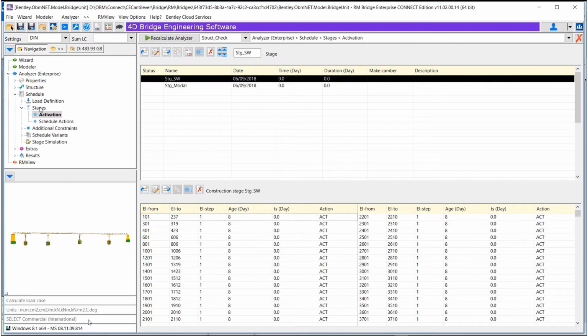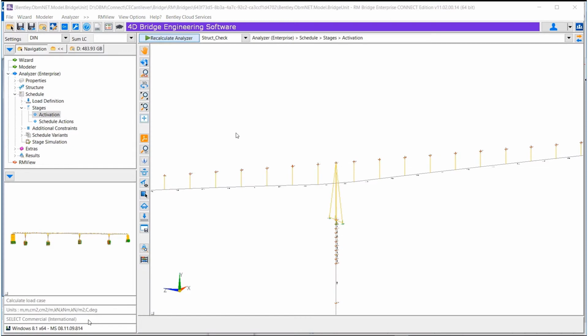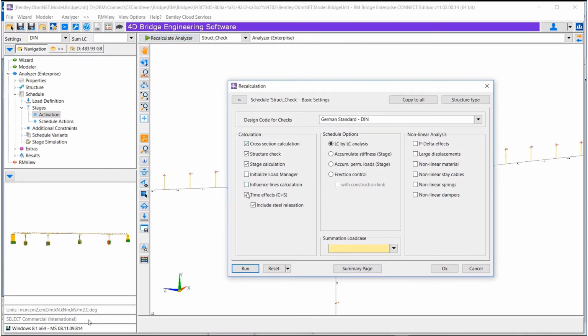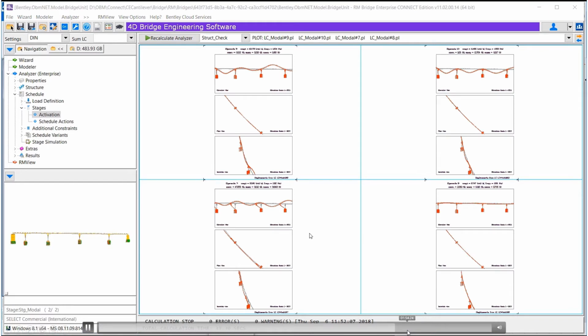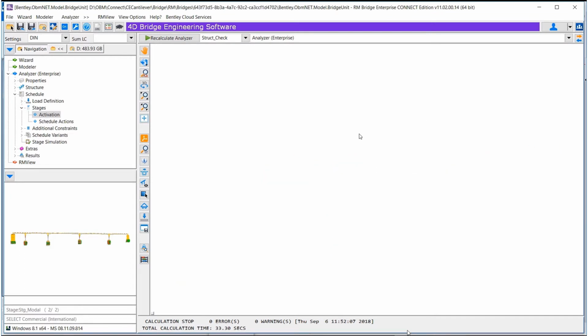It's all built up according to the stages. Remember the stages that we created, and all the properties that are coming from the model are transferred to RM. So internally, the software does a structural check and verifies if the bridge model that I just created is structurally sound, at least for dead load, right? We can apply seismic analysis there too, right? But it gives me all the information, ready to do. Here it performs seismic analysis too because it does this as a response spectra first, right?